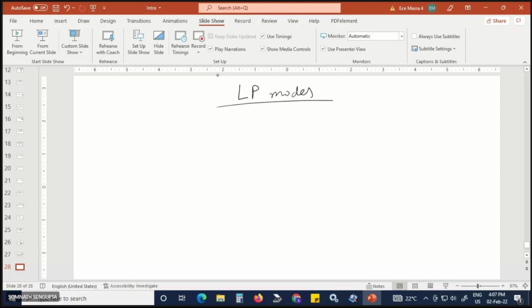So you have to use this formula, the V number: V = K0 a into numerical aperture, where K0 is 2 pi by lambda, and a is the fiber radius. And numerical aperture is root over n1 square minus n2 square.